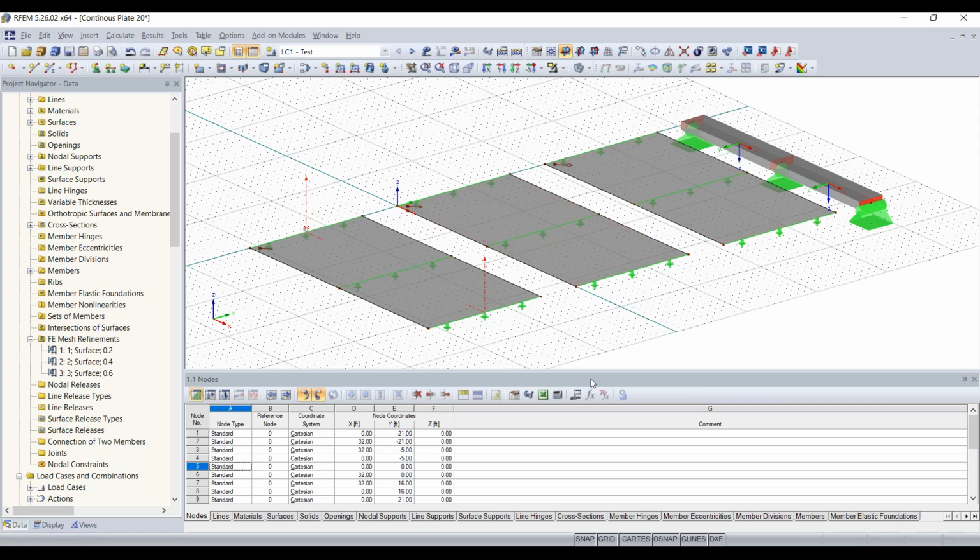once we run them. Then we want to add this section cut to these other two surfaces, and an easy way to do that would just be to hit Control and then left click, and then we can just drag that section cut over like so. You can snap to that center point again, select it again, hold Control, and then left click. And now we have section cuts on all three of our plates.